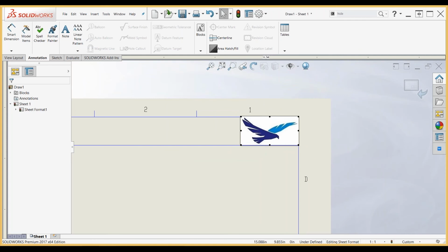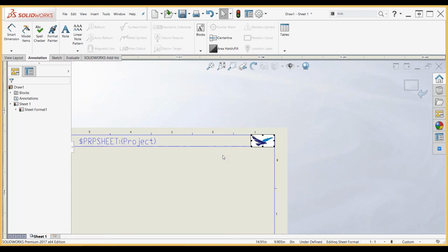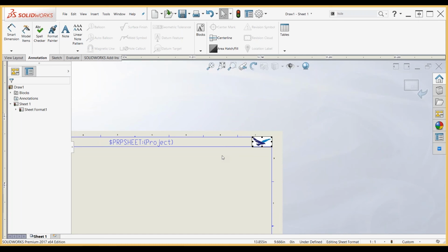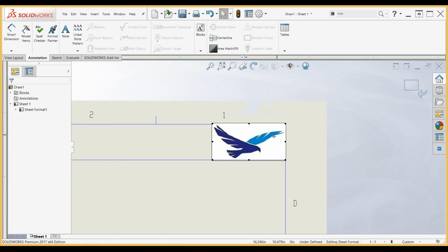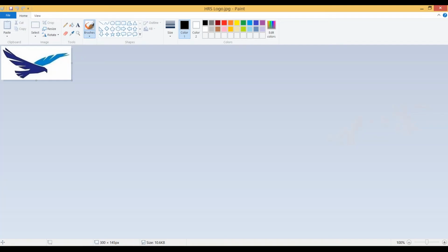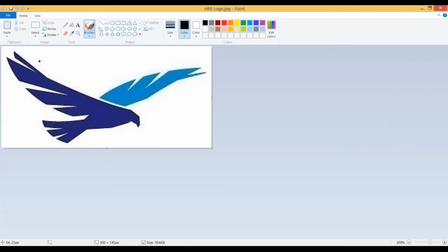Every time I open this drawing file, it's going to look at those references. So we can see here that it says, okay, do you want to update my links? I said yes, and now we have those awesome streamlines in my drawing. I didn't have to do any re-importing or anything. That happened all automatically. So one more time, just to clean that up, I'll bring the image back to the way it's supposed to be. I'll save the image, go back to SolidWorks, reopen it, and it reads that file and notices that, okay, no, it's changed, there's no more red lines there.